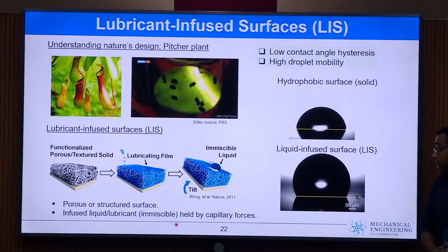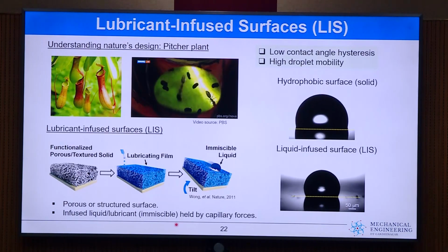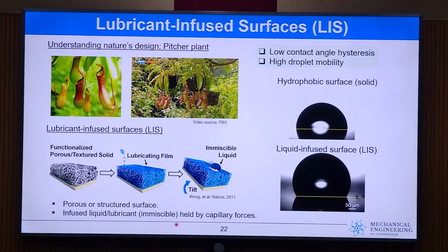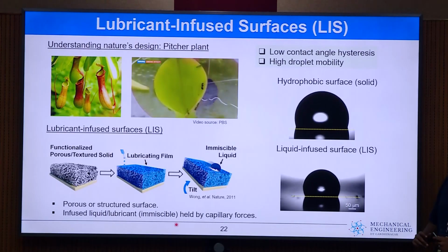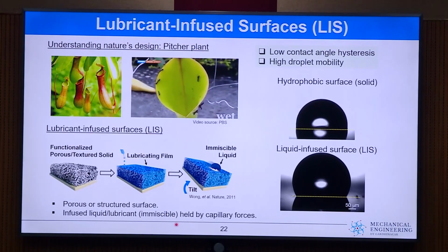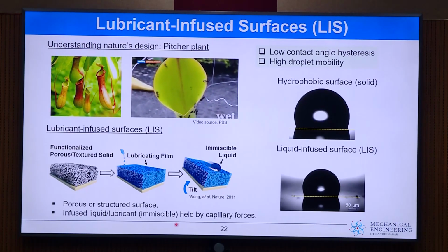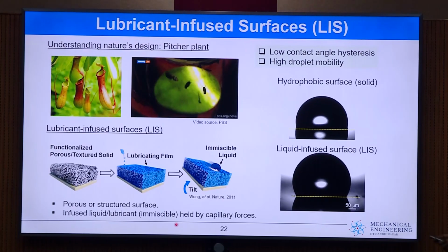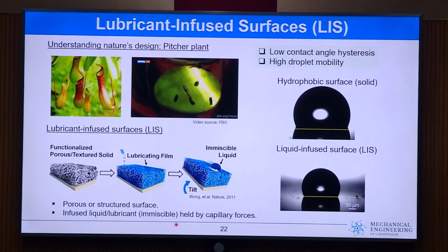And once we have a liquid-liquid interaction, it gives us ultra-low contact angle hysteresis. If you remember from the earlier talk that Professor Arvind mentioned, contact angle hysteresis is the difference between the advancing and the receding contact angle. And in this case, because you have a liquid-liquid interaction, you have much lower contact angle hysteresis.